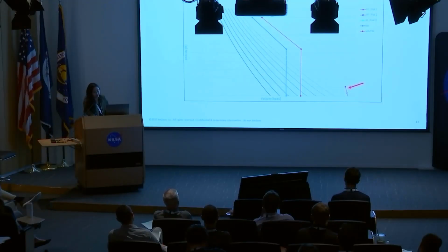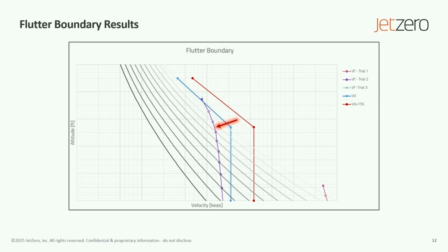So we did our second trial, which is increasing GJ-EI ratios from our baseline wing to match our flutter-free wing. And we got this right here. It did not really pass the flutter requirement. It undershot quite a bit, and so we're like, okay, the first two methods, we just changed the stiffnesses, constrained them, and it was kind of a shot in the dark. Like, oh, we have this wing, we're going to try and match it.